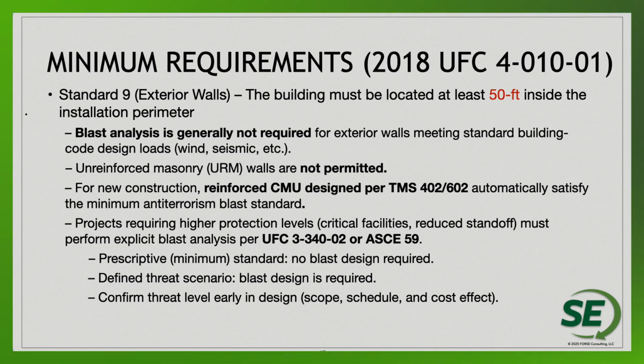So to summarize this, or to add more to this concept, unreinforced masonry is not permitted. For new construction, reinforced CMU designed per TMS 402-602 automatically satisfies the minimum blast requirement when standoff distance requirements are met. And then if the facility requires more than the baseline level of protection, let's say it's a critical facility, or it's a building with reduced standoff, then a full blast design per UFC and ASCE 59 is mandatory.